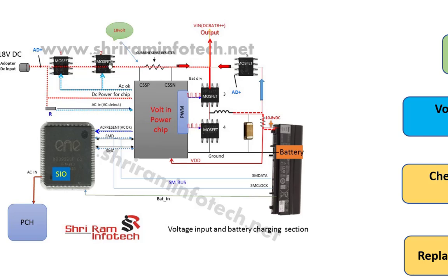Sometimes the MOSFET is short. If the MOSFET is short, then it will show a zero resistance or the buzzer will sound. So make sure this MOSFET is okay.